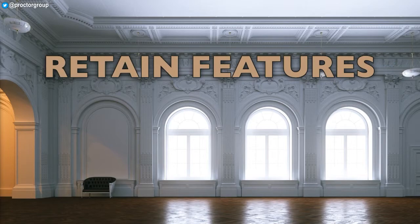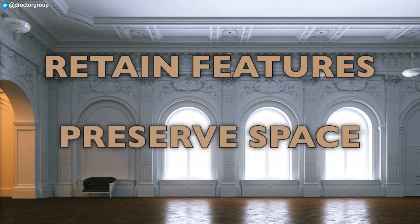Significantly improving technical performance while maintaining these aesthetic qualities poses a number of challenges. Ensuring that internal spaces remain large enough to be fit for purpose is of particular importance, as is minimising the effect of upgrades on moisture movement. Strategies to upgrade the energy performance of existing buildings must therefore be carefully considered, and considered holistically, as actions affecting one aspect of the building may have unforeseen consequences in another.